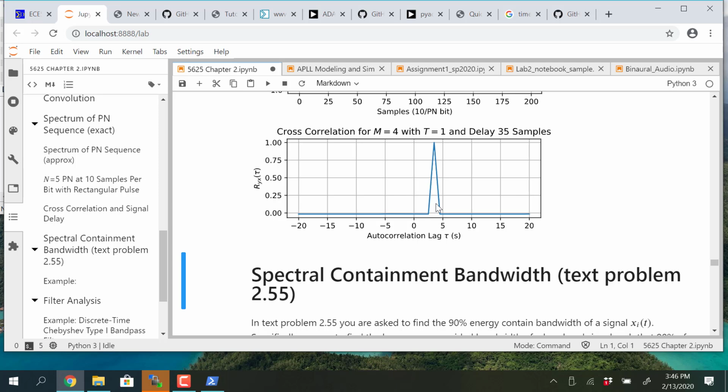In spread spectrum for third generation cellular, they have the ability to do what's called a rake receiver, which correlates with multiple correlators and tries to reassemble the signal so it can get a stronger signal by combining the main peak and then the weaker peaks. The signal arrives at us through multipath, and we're trying to harvest as much out of the channel as possible by combining signals.